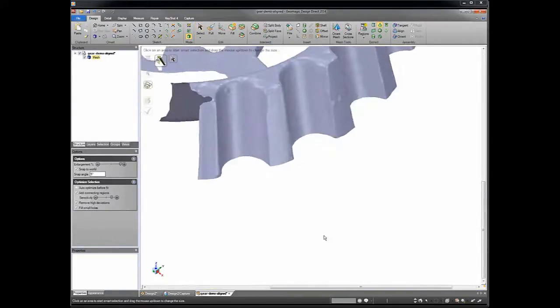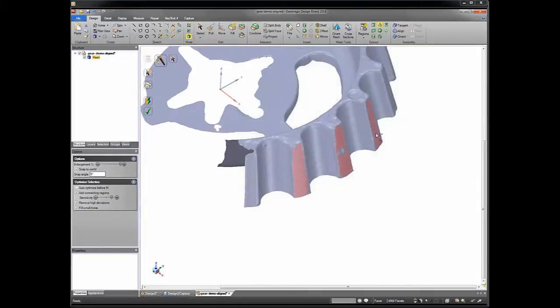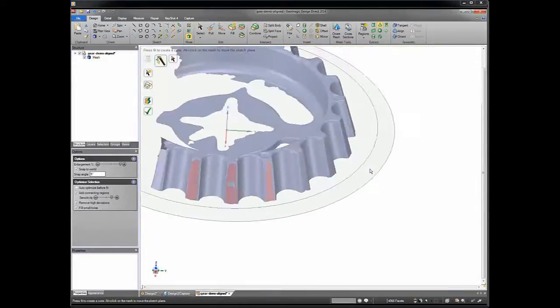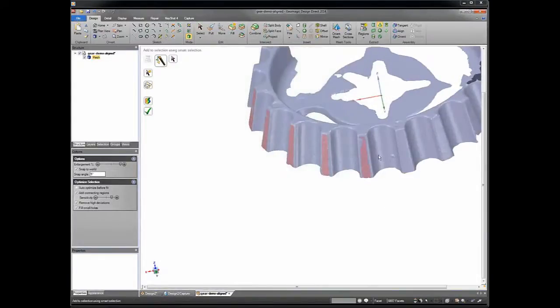Now, I alluded to before something called Smart Select. Smart Select allows me to click and just drag up or down on the screen, and it will vary in real time what the selection set is. So because I have it on a cone, you can see if I just give it this amount of data, that's not nearly enough to extract that large outer cone. So I hold down Shift, I give it a little bit more data, starts to refit, and slowly I'll start getting the cone shape I want, because again, these are just little slivers of data that define this outside cone.